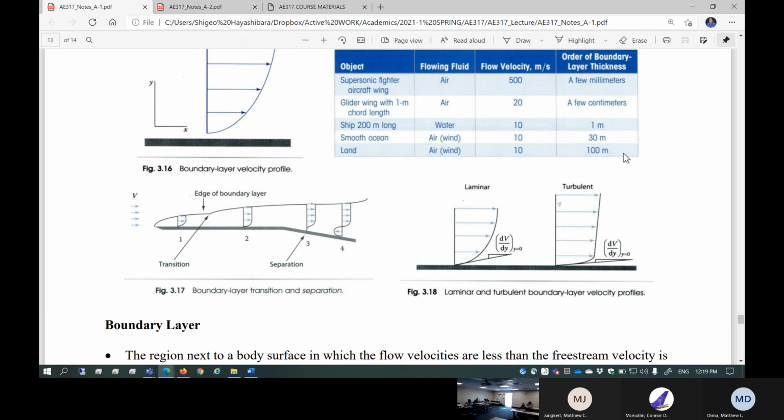In other words, if a car is placed in a wind tunnel and you turn on the wind coming in, a boundary layer is formed up from the ground. So the car is actually sitting inside of the boundary layer. What are you testing for in that situation? Ground vehicle wind tunnel testing is not easy because usually people need to suck the boundary layer out. Otherwise, you're testing everything inside of the boundary layer.